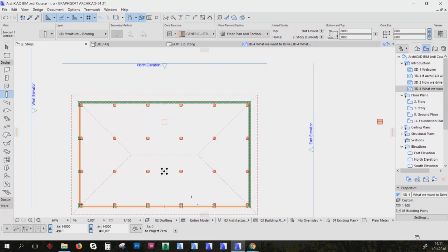Gravity, and another one is measuring. If you want to quickly measure between 2 points without having to put a dimension line, it is this tool here, but just pushing M turns on the measuring tape and gives you all the information there, so you don't have to take your mouse up to the screen and turn it on and come back down.